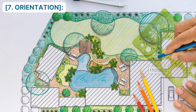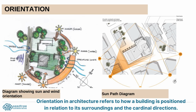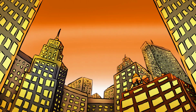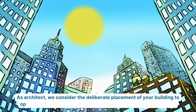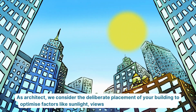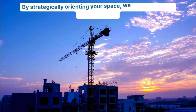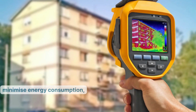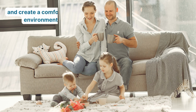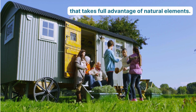Number 7. Orientation. Orientation in architecture refers to how a building is positioned in relation to its surroundings and the cardinal directions. As architects, we consider the deliberate placement of your building to optimize factors like sunlight, views, prevailing winds, and climate. By strategically orienting your space, we can enhance its functionality, minimize energy consumption, and create a comfortable environment that takes full advantage of natural elements.